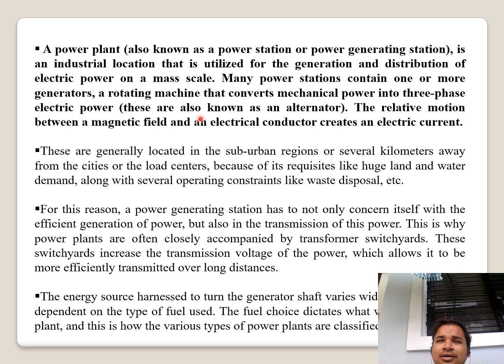So the completion of the circuit, or the completion of the direction of the current, is important. The potential difference between the electricity carrying wire and the ground is 240 volts AC. If you touch that wire, the potential difference being very huge, 240 volts, it will surely find the way to the ground, and with the circuit completed, you will experience an electric shock. So this is the difference why the bird does not get affected and why a human gets affected.